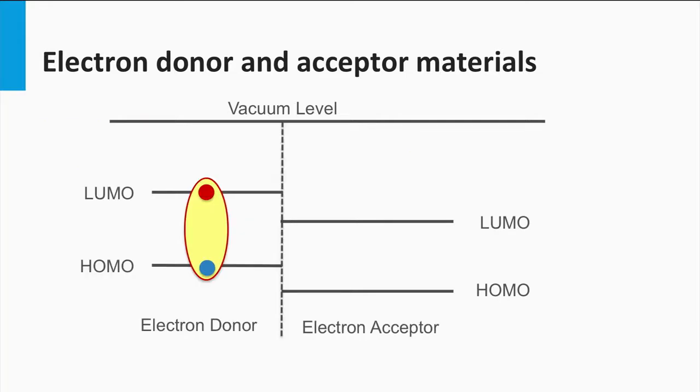Another important aspect of exciting charge carriers in organic materials is that it differs from that of the inorganic semiconductor materials discussed so far. In inorganic semiconductors, we can excite an electron from the valence band to the conduction band, leaving a hole in the valence band. In a semiconductor, such an electron-hole pair is weakly bound and both entities are easily separated and can diffuse away from each other. In organic materials, this is not the case.